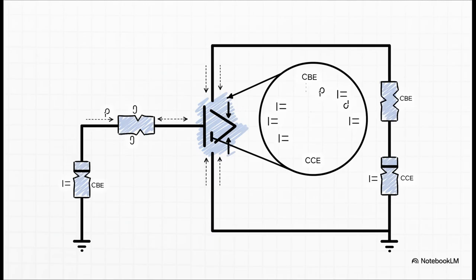So let's just recap what's limiting our frequency response. It's these two forces, capacitance and inductance, and they are everywhere. You've got them in the wiring, in the components. You've even got this pesky interelectrode capacitance that's literally built inside the transistor itself, between parts like the base and the collector. You can't escape it. And all these tiny individual effects add up, and that's exactly why that nice flat performance curve we saw eventually has to drop off on the high and low ends.